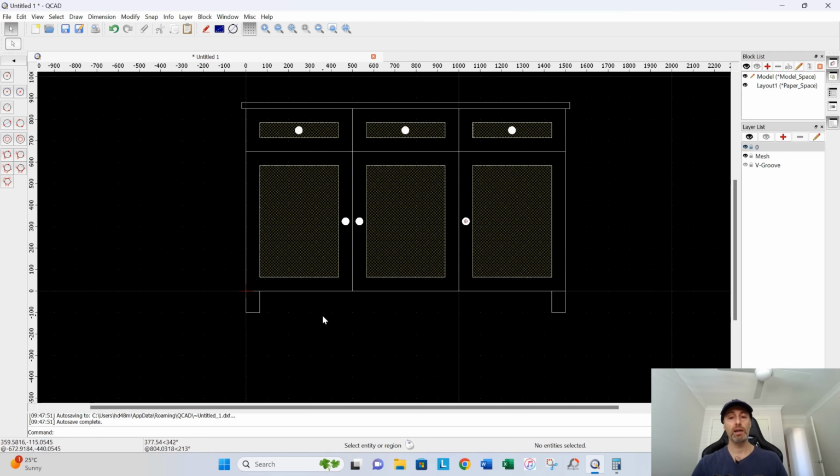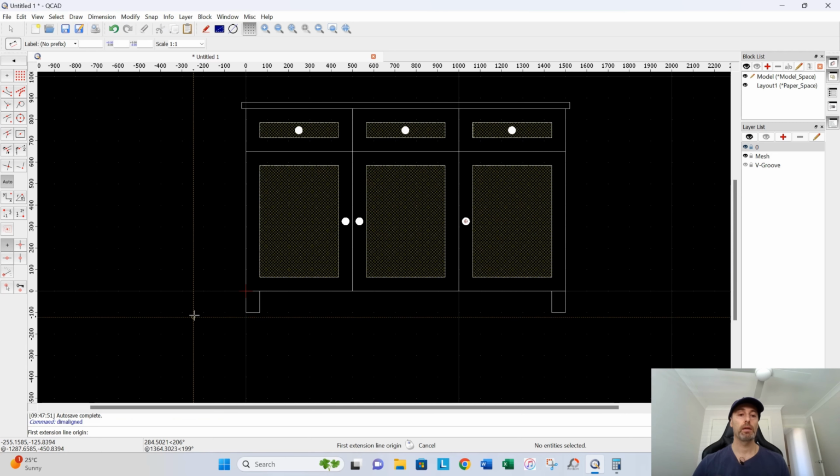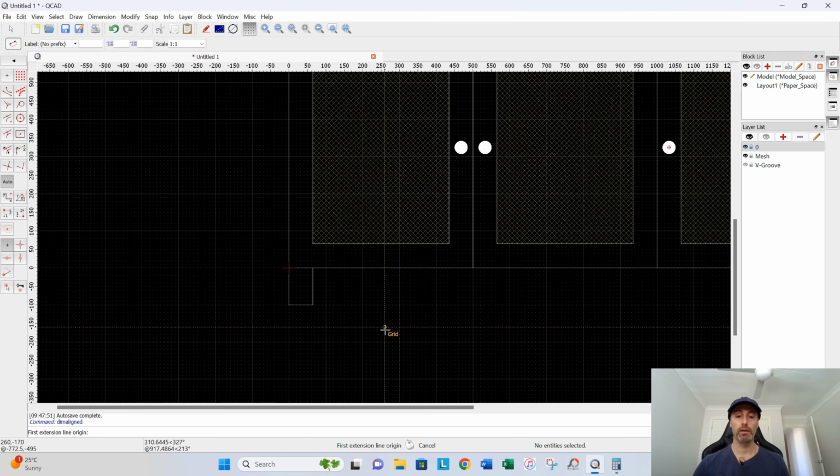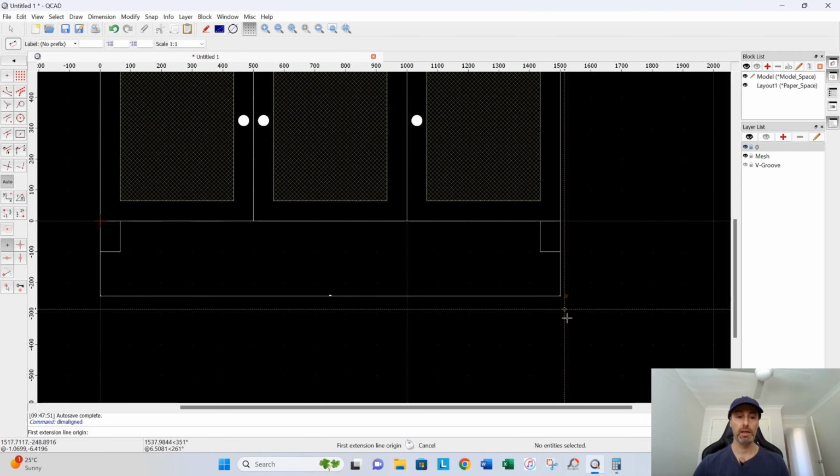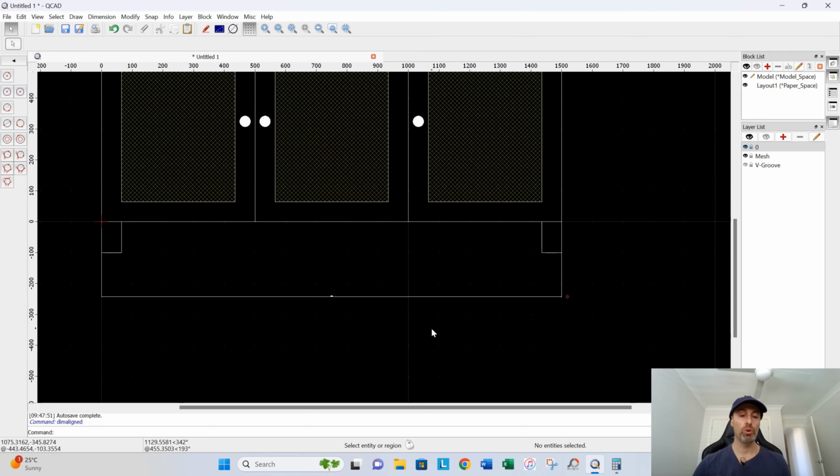The last thing I'll show you how to do now is to dimension it. I don't want this video to go too lengthy for you, it'll bore you. But let's quickly dimension it, and we'll put a title on the front, and then I'm going to show you how to quickly save it and print it. So dimensions, which is over here, align. So let's just do a measurement. You're going to snap it in that corner there, to that corner there, and come down. Now, you can see that that looks awful. My dimension lines are touching. You can't see the measurement at all, and this is all because it needs scaling.